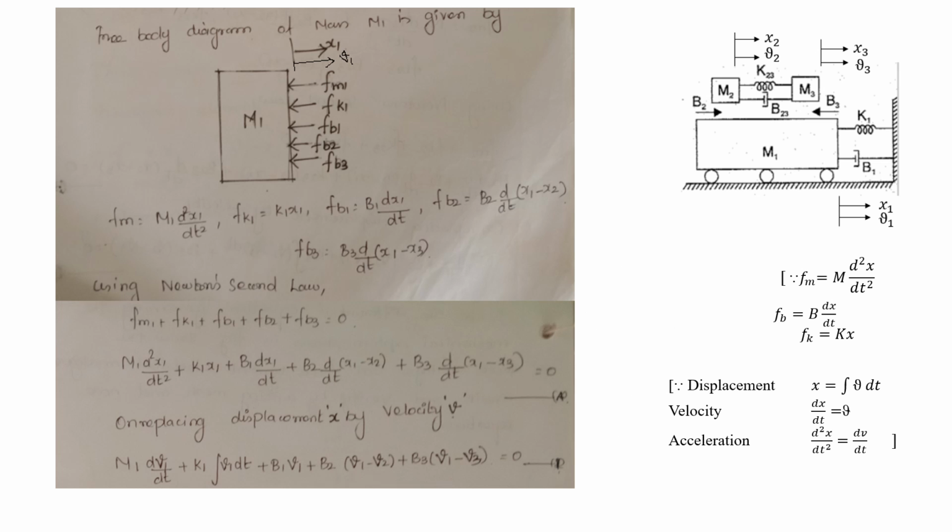See here, the free body diagram for mass M1 is given by this. To draw the free body diagram for mass M1, first we have to represent the mass M1 in a square box. By seeing this question, we have to draw all the applied as well as opposing forces. Immediately after drawing the mass M1, we have to represent the corresponding outputs. For mass M1, the outputs will be x1 as well as v1.